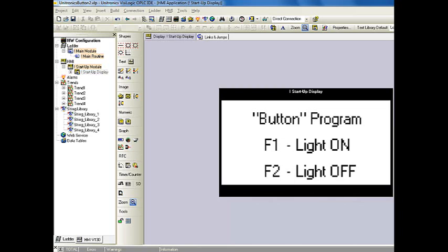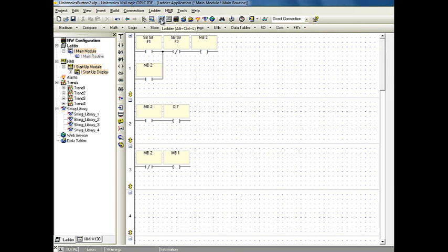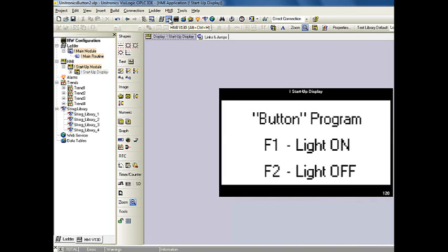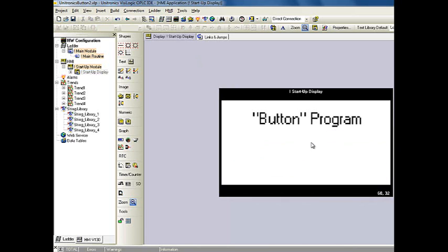Next, we will program the HMI, the human machine interface, that is what shows up on the screen. To get to this screen, we pressed this button. We were looking at the ladder logic view, but when we press this button, we can switch to the display view, or the HMI view. When we're done, it's going to look like this. To show how these are created, I will delete both of them and reinsert them.